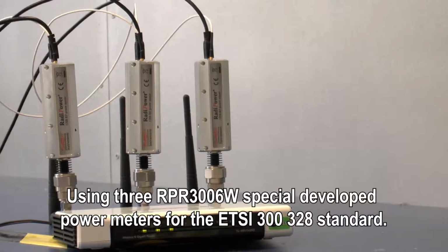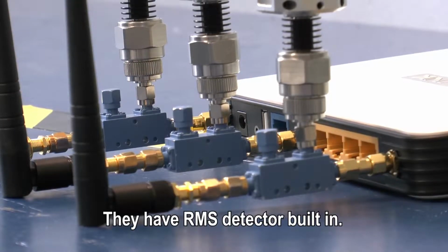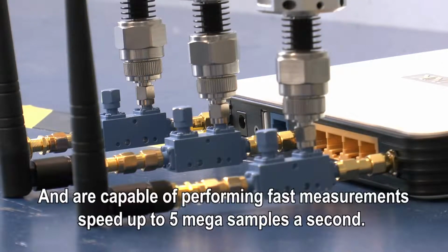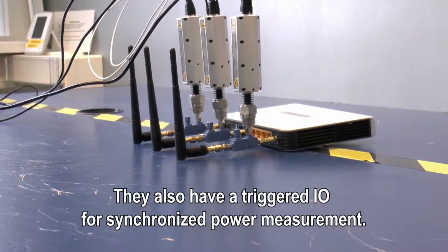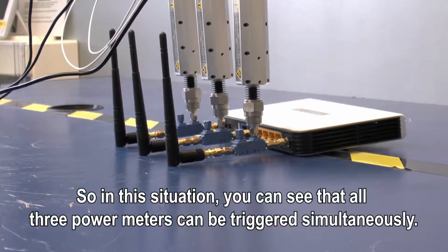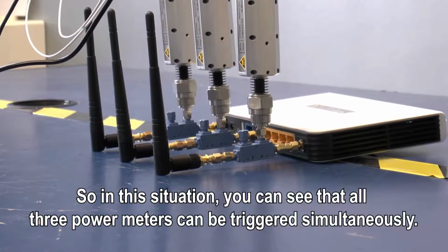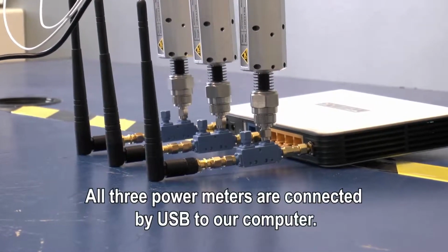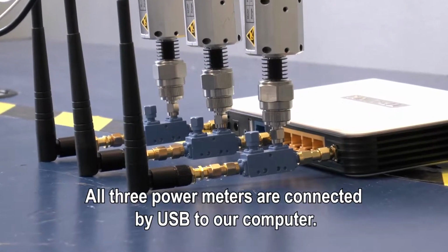for the ETSI 300-328 standard. They have RMS detector built in and are capable of performing fast measurements speed up to 5 megasamples a second. They also have a triggered I/O for synchronized power measurement. So in this situation you can see that all 3 power meters can be triggered simultaneously. All 3 power meters are connected by USB to our computer.